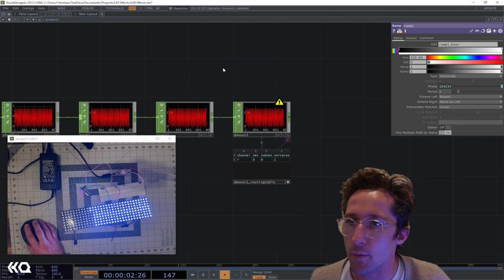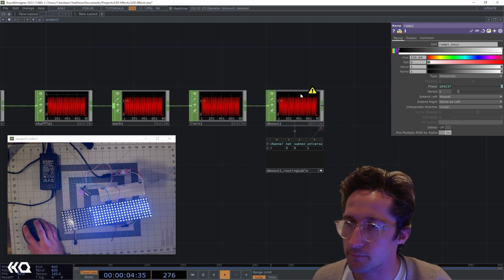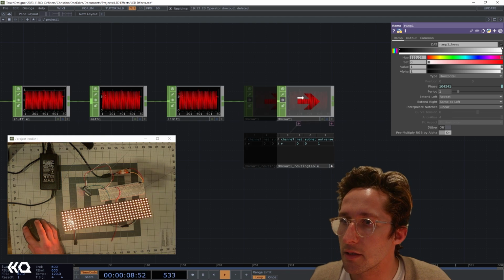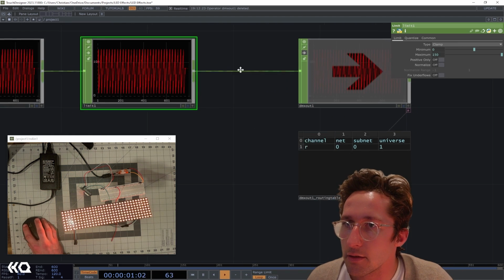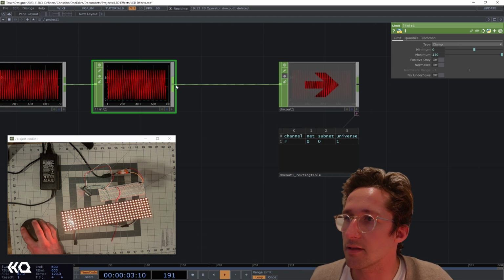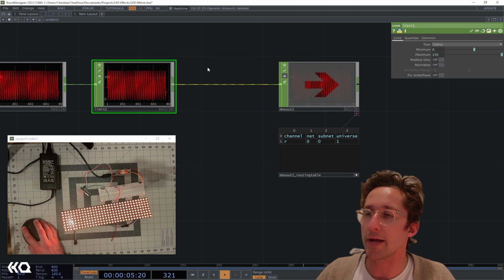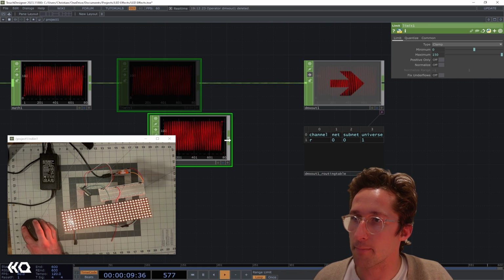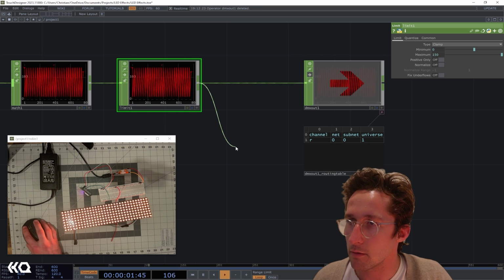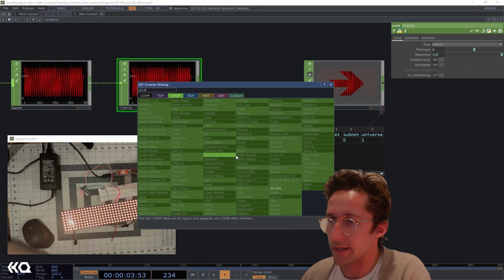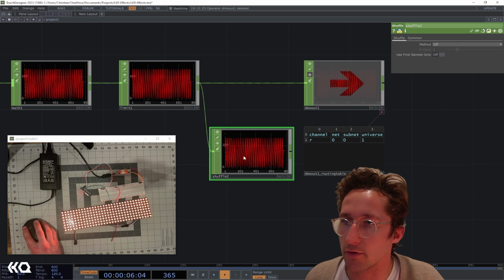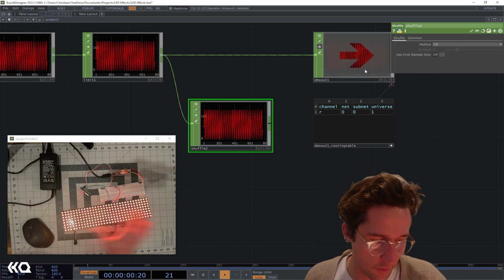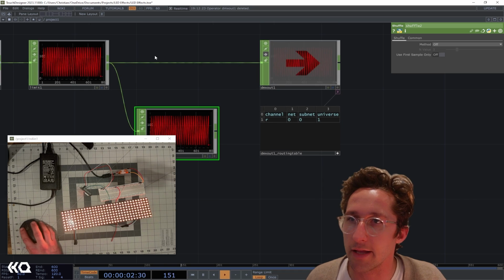And if we want to fix the first one, what we need to do is see that the DMX channels can only handle 512 addresses. So we'll need to split our channel into 2 different universes to cover the entire 256 LEDs.